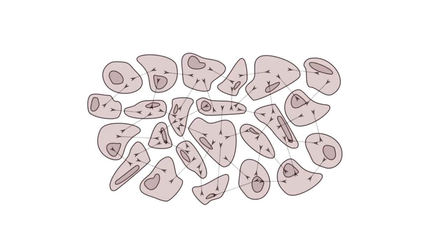Some soils, like clay, do have a certain amount of natural attraction between particles, called cohesion, but it's not enough on its own to resist significant forces. In other words, you can't make a rope out of soil. It has no strength against tension. So if you build a tunnel in soil, you have to replace the support you removed with some other way to transfer the load of the soil above.